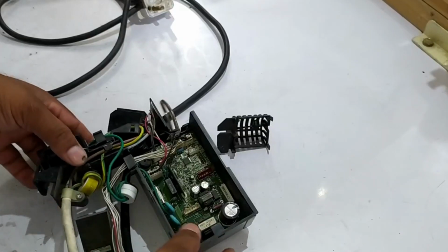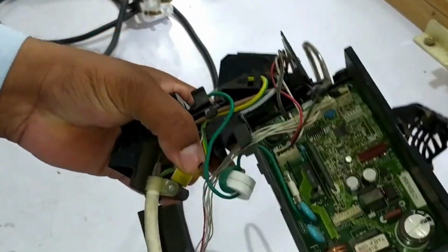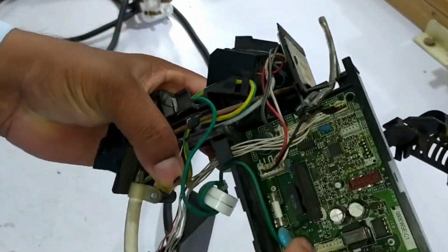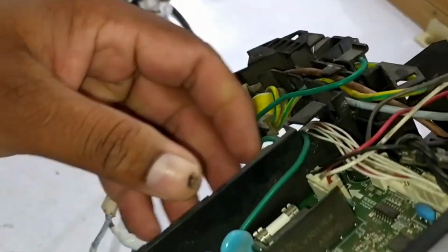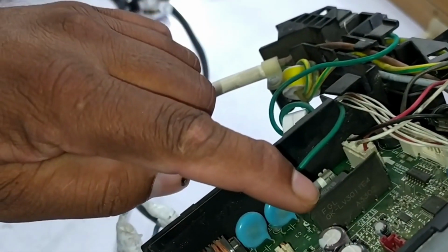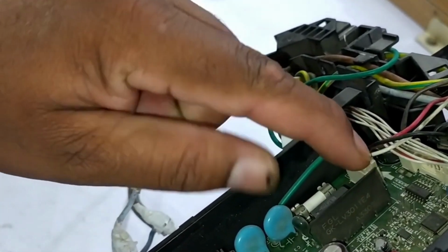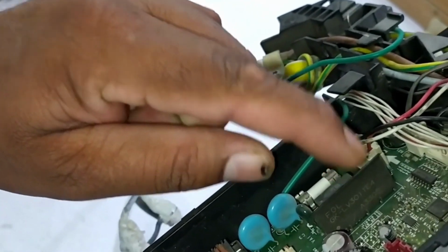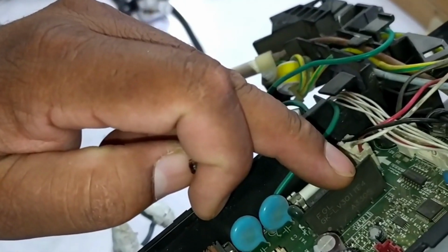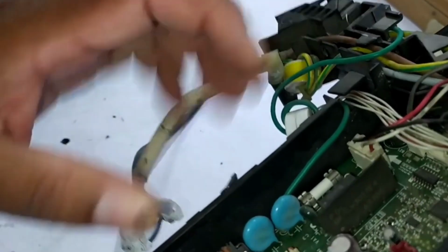Now, let's discuss what could be wrong inside the indoor PCB and how to fix it. One of the critical components responsible for communication between the indoor and outdoor units is the communication IC. If there is a fault in the indoor PCB, this IC might be defective. To troubleshoot, check the communication IC using a multimeter to ensure it is receiving and sending signals properly. If the IC is faulty, replace it with a new one. After replacing the IC, the communication between the indoor and outdoor units will be restored and the error will be resolved. This step is crucial in ensuring that the indoor unit is functioning properly before further diagnosing the outdoor unit.